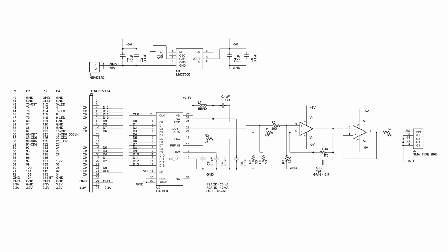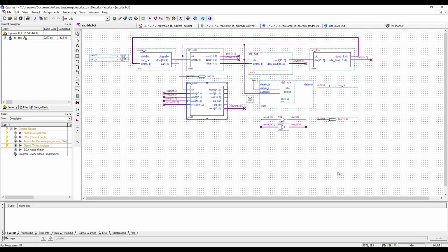In the FPGA, the upper bit is inverted, since the DAC output is unsigned. Also, I did a little trick with the double data rate output. This provides an inverted clock at the same frequency as the input frequency, and this is used to drive the DAC.